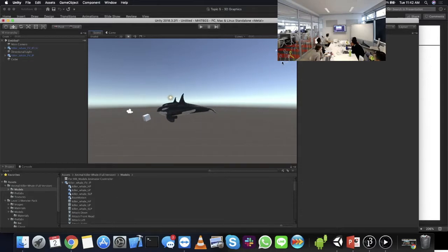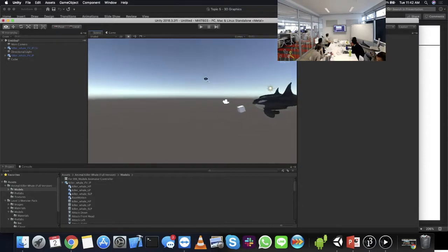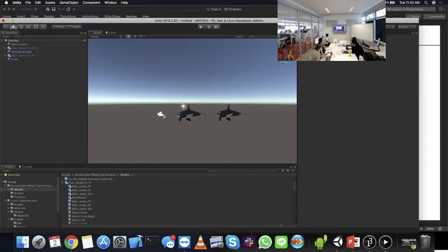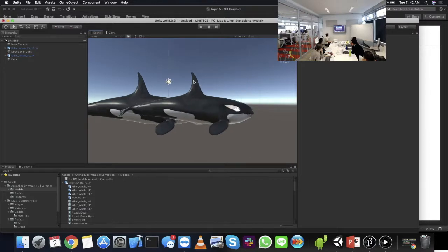But underneath that, you'll see that it has this little thing with a triangle and then it says left, and the left will change depending on my view, or it'll just say perspective. But if I click on that triangle thing, you'll notice it changes into three parallel lines, and that's changed it from perspective view into isometric or orthographic view, which we can see now it says isometric. Isometric and orthographic are basically the same thing.